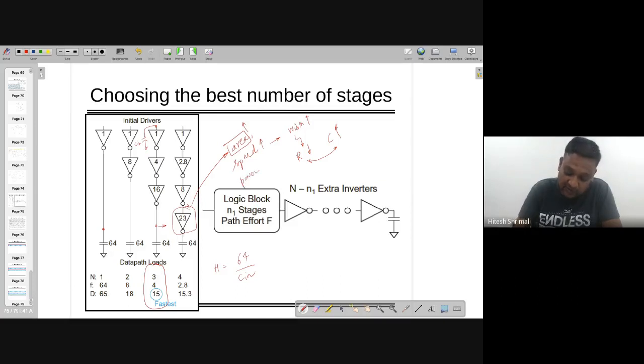As you have more width, of course the power will be more, because of the current equation. If I'm writing it for just NMOS, it is mu n Cox W by L, (VGS minus VTH) times VDS minus VDS squared by 2. You can see that as you are increasing W, most of the things here are constant. The only things governing the current equation are W and L. L is also relatively constant because you don't touch that. It's going to be the minimum one.